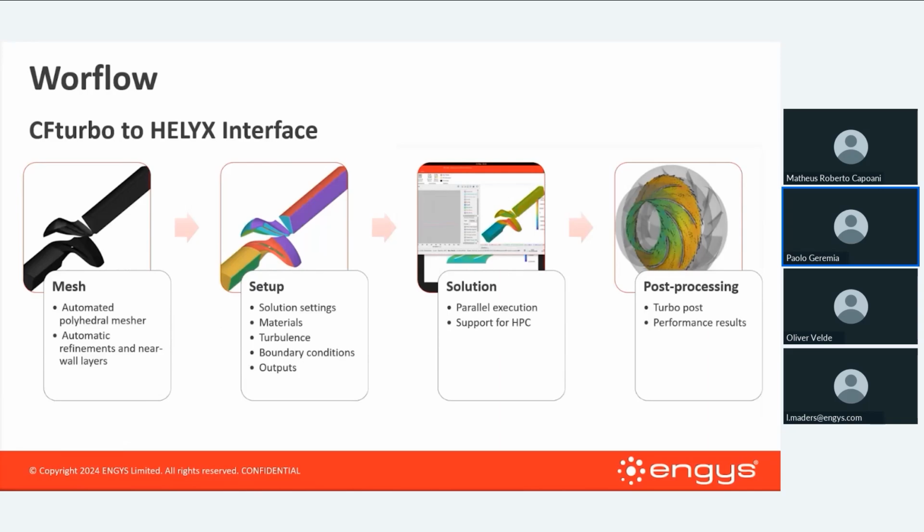Once a computational mesh is available, the setup phase will be done in terms of solution settings, material properties, turbulence models, boundary conditions, and output responses, which are quantities of interest, such as efficiency, power, and head of the pump that we want to measure.